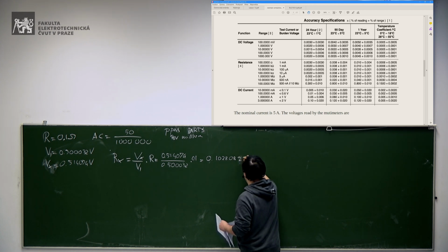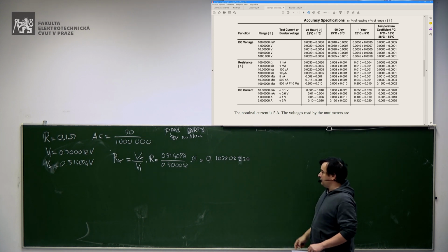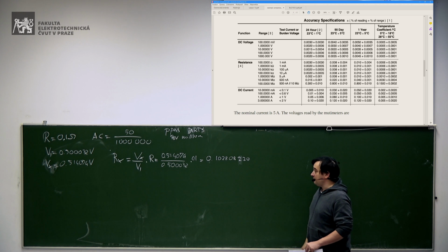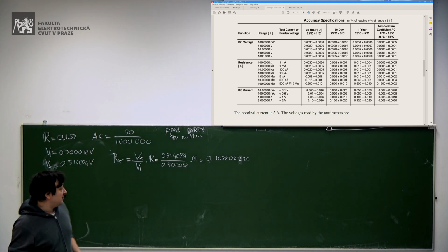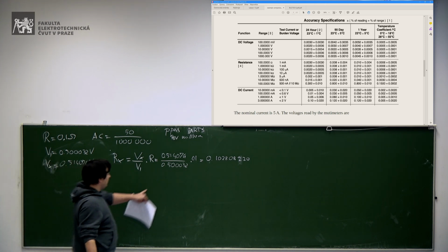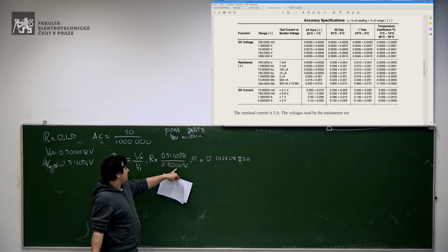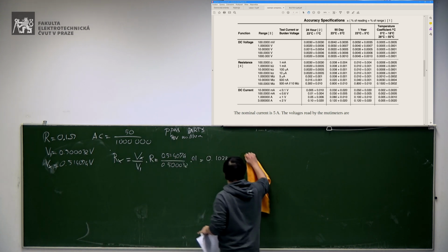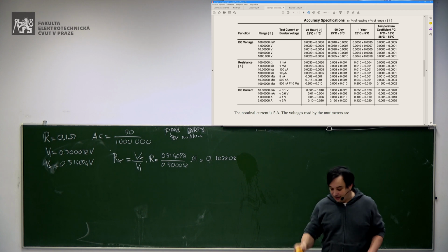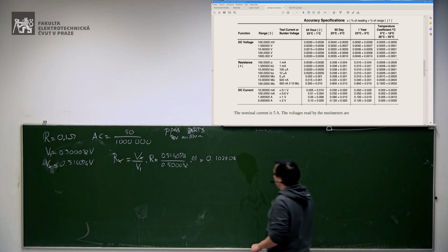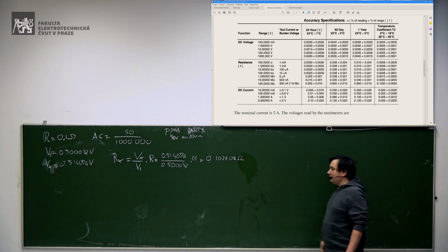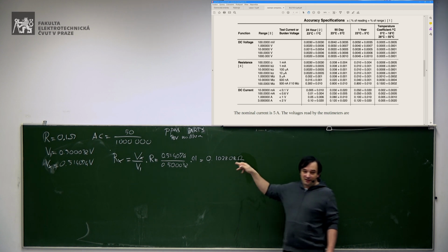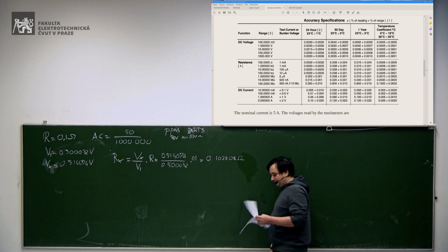Now, typical mistakes that I've seen in exams is to see too many digits after the decimal point. Why? Because the calculator is giving you this digit, and you say, why not write them down? But be careful: if I'm using a multimeter with 6.5 significant digits, the result cannot have more than 6 digits. If you have the measurement done with 6 digits, also the result must have at most 6 digits, not more, because those numbers are given by the calculator, not by the measurement instrument, okay?